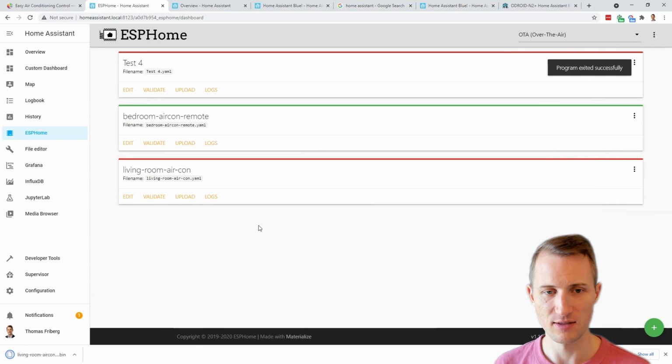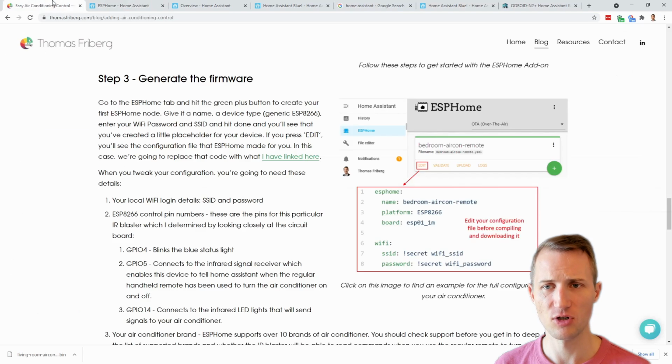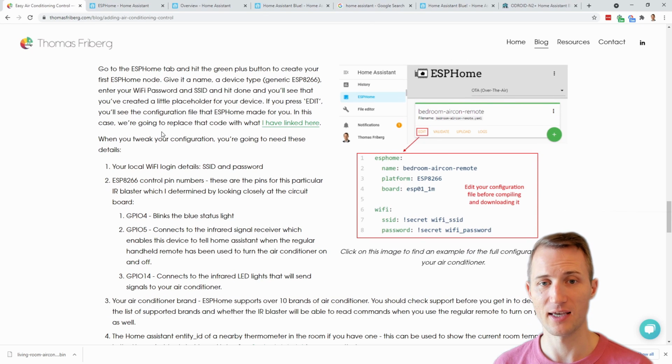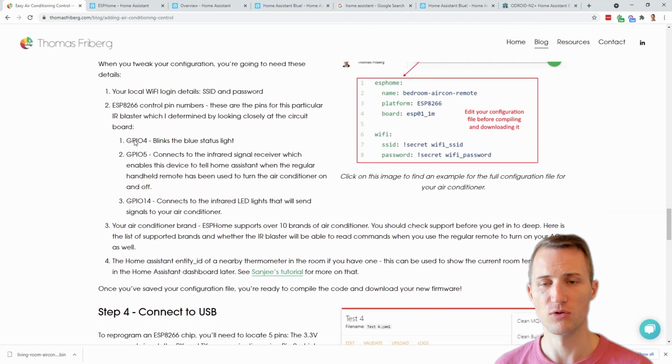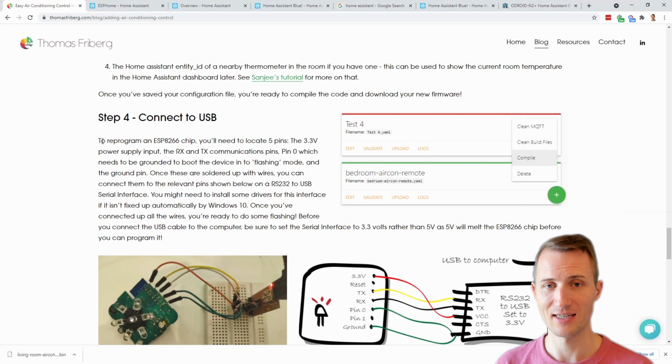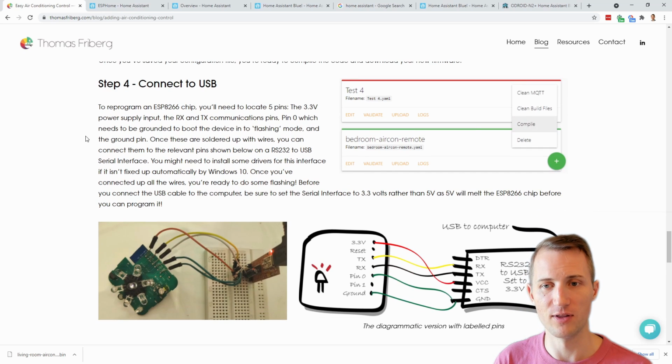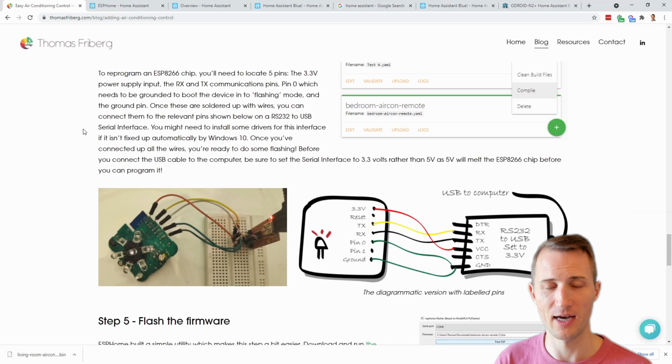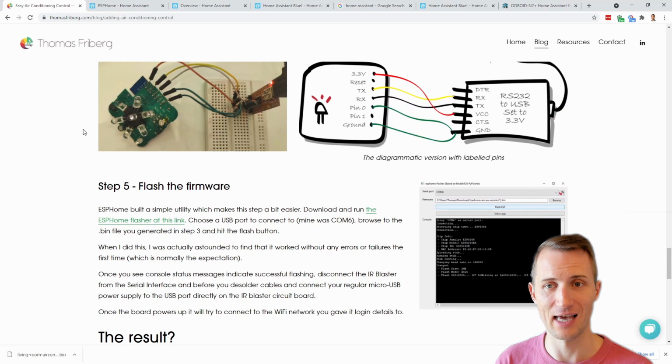At this point, you'll see it's downloading in the bottom left there, and that .bin file is something that I can now send over to the device. So how are we going to do that? Well, we'll have to connect it to our computer. So here are some instructions to do that. Now, for this particular controller, we had some exposed pins that were nicely labeled. Not all of them do, but that's why I preferred this one.